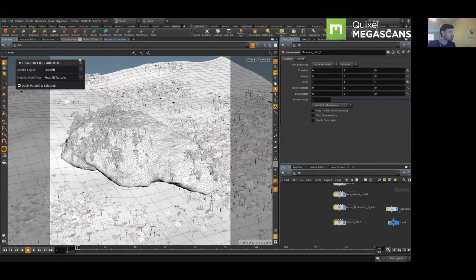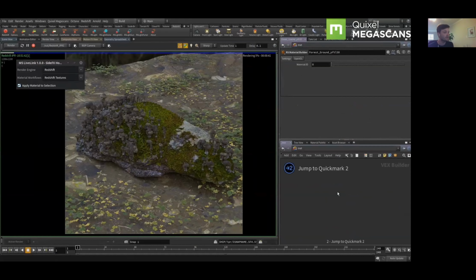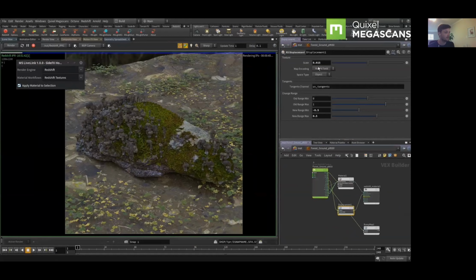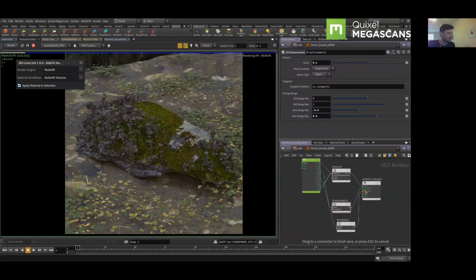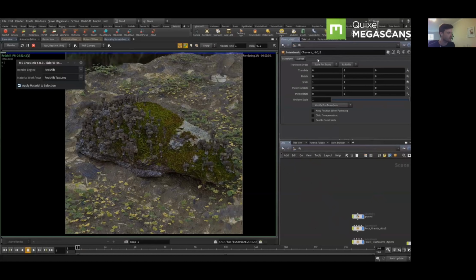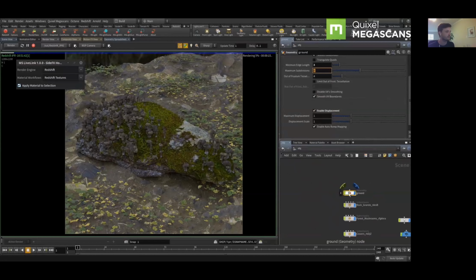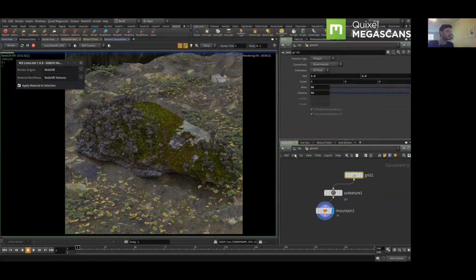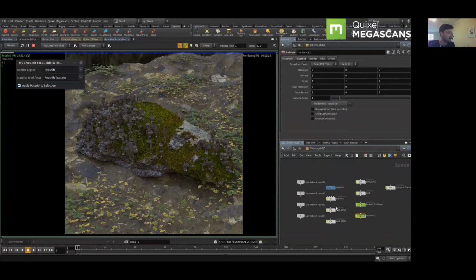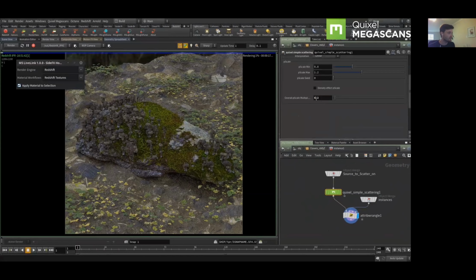If we were to launch a test render now, you basically get all of your materials perfectly calibrated and set up for you. Here we're just tweaking some displacement settings and connecting up the bump map to the material, which with Redshift is an optional step. So it's disconnected by default, but you can hook that up if you want to. And with a few more tweaks to displacement and tessellation, scatter density, and some shader setups, you can very easily achieve a very, very nice result.